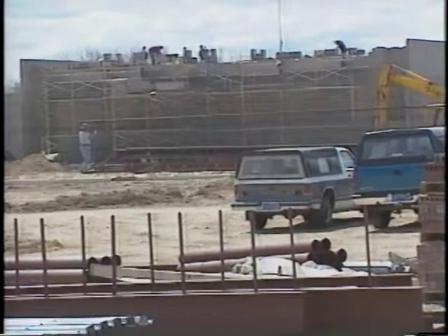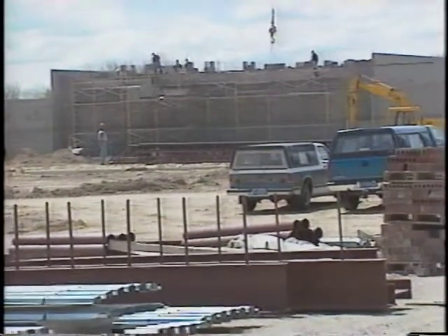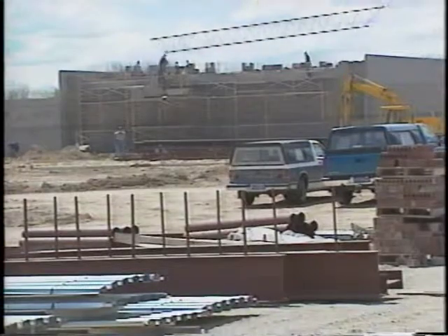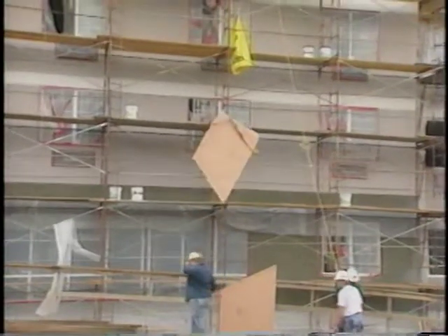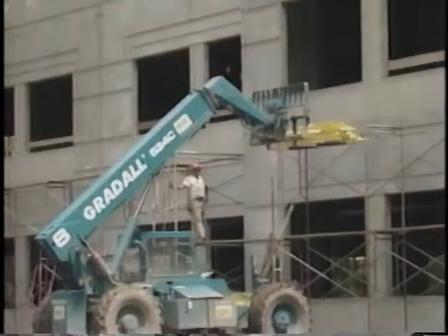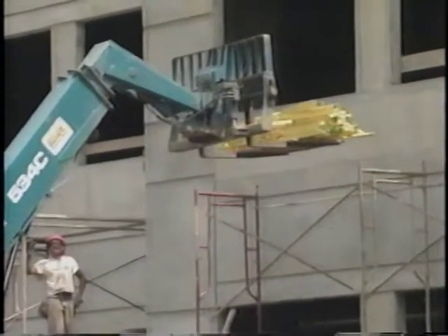In addition to load capacity and falling objects, another consideration with material handling is actual contact with the scaffold. Use tag lines when the possibility exists for a load to swing and hit the scaffold. Operators should also make sure their equipment does not strike the scaffold.